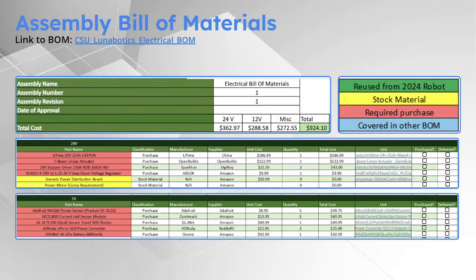Another thing to implement is periodic checks over all your cables. Look for, they call them preventative maintenance checks and services. Go over, make sure there's nothing that's broken. Look over your insulators, making sure there's no cuts, no gashes, things of that nature.